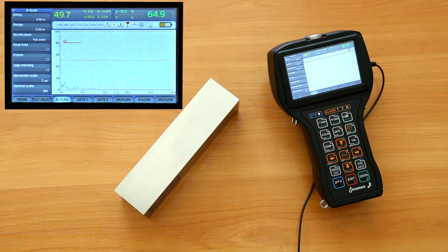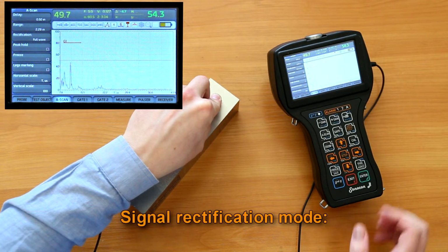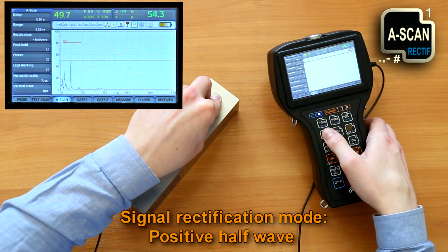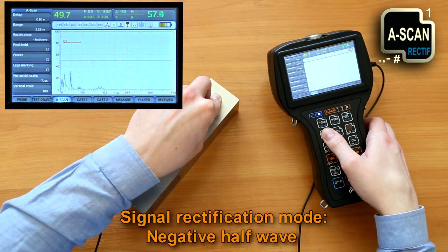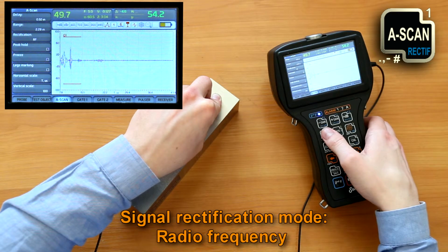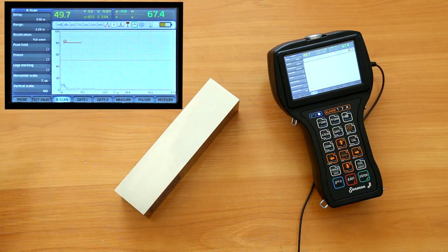Second function plus A-scan, and successive presses of the A-scan button will cycle the signal rectification mode: full wave, positive half wave, negative half wave, radio frequency, and go back to full wave. Press second function or exit button to quit this cycle.